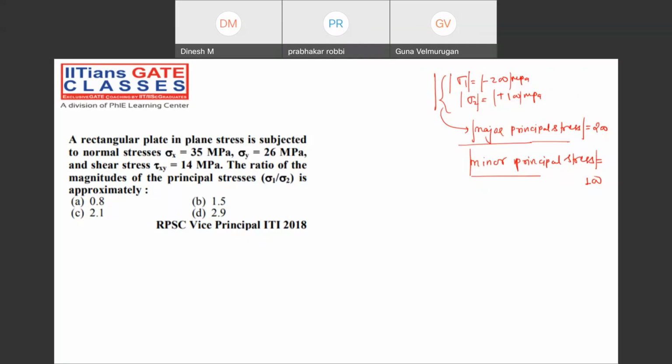All the problems that you are solving use the analytical method. The graphical method is the Mohr circle. Whatever loading condition has been given to you is called a complex loading condition. What is the meaning of complex loading condition? When normal stress and shear stress are both acting, that is called a complex state of stress. For a complex state of stress, we have seen the analytical method as of now. Somebody may ask you to find the maximum principal stress and normal stress or shear stress by using the graphical method, then there is the Mohr circle.